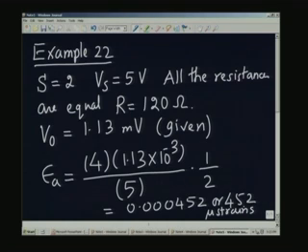So, the strain of the strain gauge element, which gives an output of 1.13 millivolts, when the 4 resistances are of equal value in the balance condition, and each resistance is equal to 120 ohms, gives me for 1.13 millivolts a strain of 452 microstrains. So, we are talking about very small changes in the length. 452 microstrains is nothing but 452 into 10 to the power of minus 6, which is equal to delta L by L. So, you can find out if L is given, delta L will be 452 into 10 to the power of minus 6 of that length L.